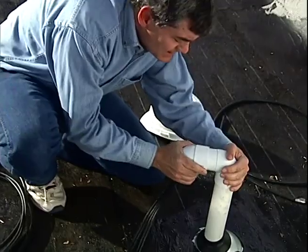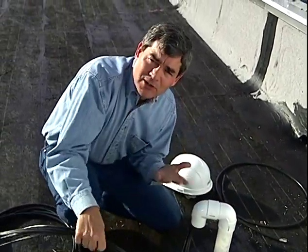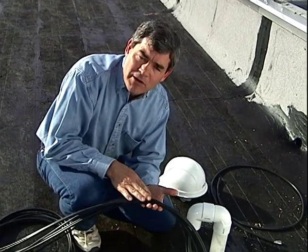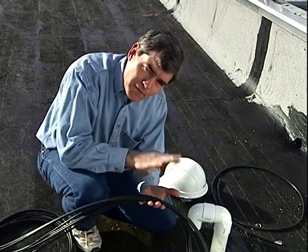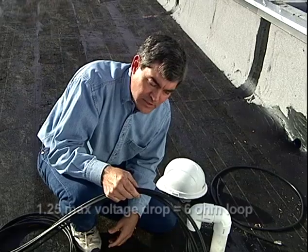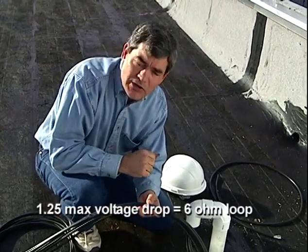Now, since it's passing the DC operating current to the LNB, about 200 mils per LNB, the DC characteristics of the coax cable is very important. Now, the maximum voltage drop from the receiver to the LNB should not exceed 1.25 volts. This works out to a maximum loop resistance of about 6 ohms.